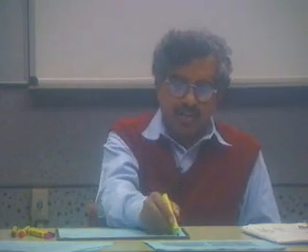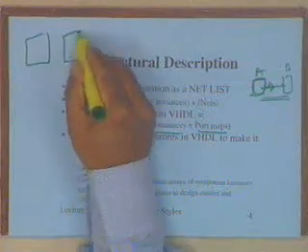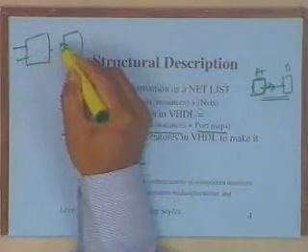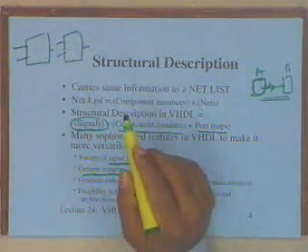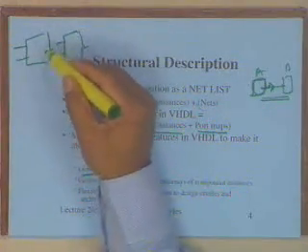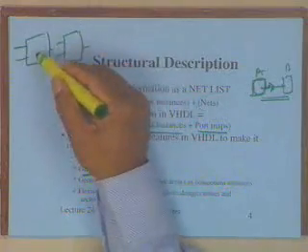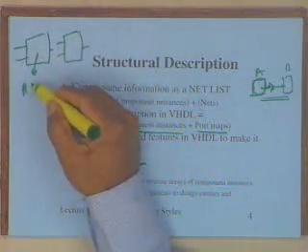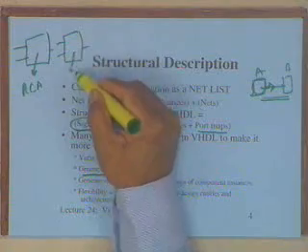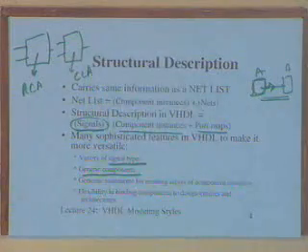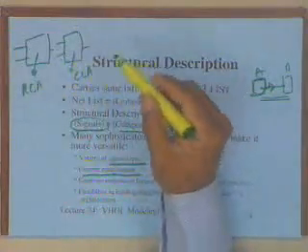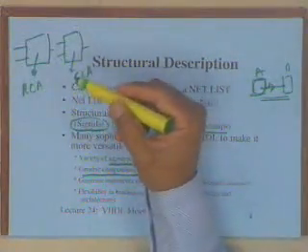I want to consider two adders. Both of them are black boxes, with the same inputs and same outputs. But internally I can bind each to a different architecture. I can bind one to the architecture of a ripple carry adder, and the other to the architecture of a carry look ahead adder. Exactly the same interface as far as the I/O is concerned, but two different architectures.